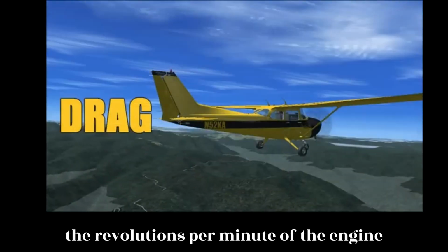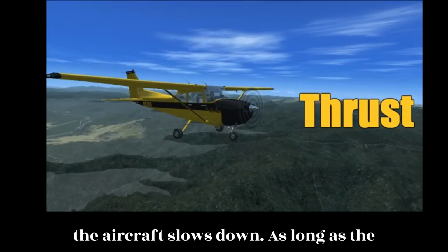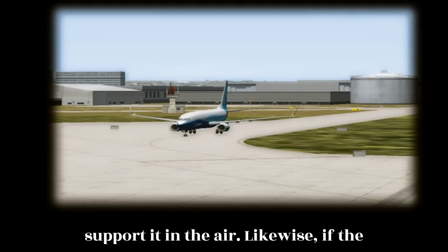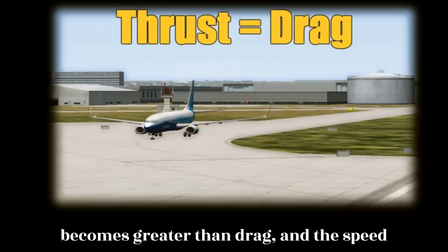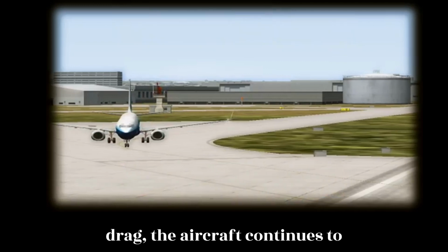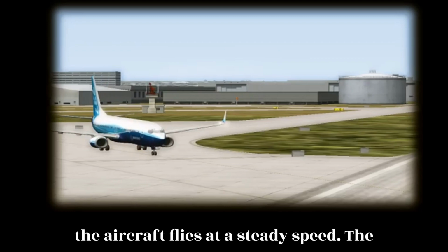If the revolutions per minute, RPM, of the engine is reduced, the thrust is lessened, and the aircraft slows down. As long as the thrust is less than the drag, the aircraft travels more and more slowly until its speed is insufficient to support it in the air. Likewise, if the RPM of the engine is increased, thrust becomes greater than drag, and the speed of the aircraft increases. As long as the thrust continues to be greater than the drag, the aircraft continues to accelerate. When drag equals thrust, the aircraft flies at a steady speed.